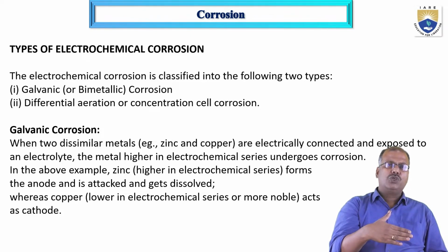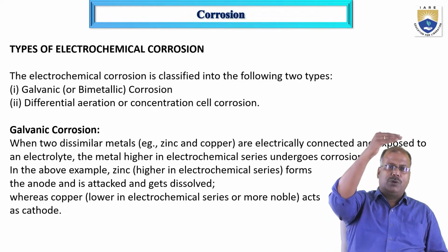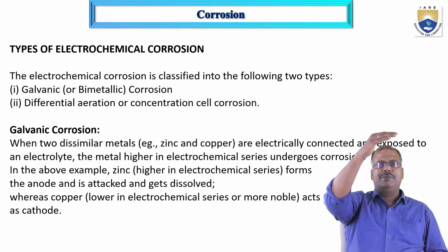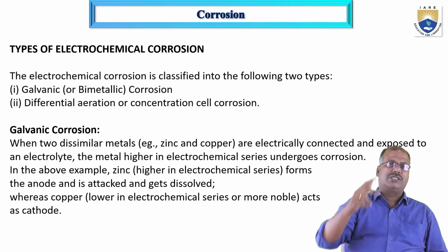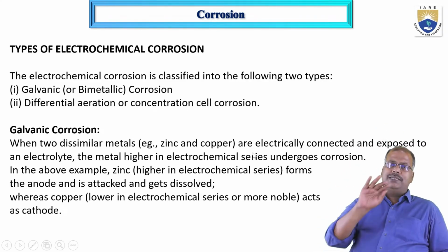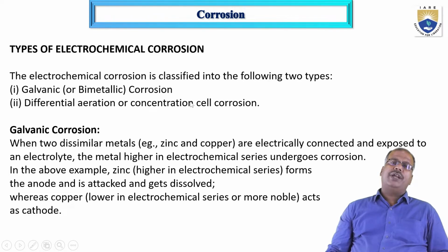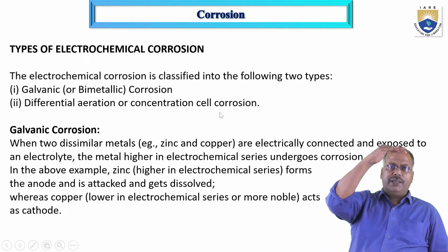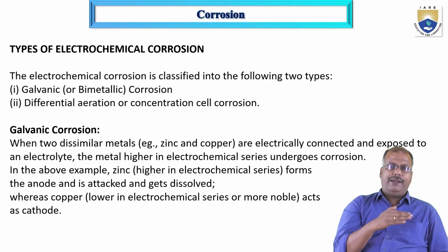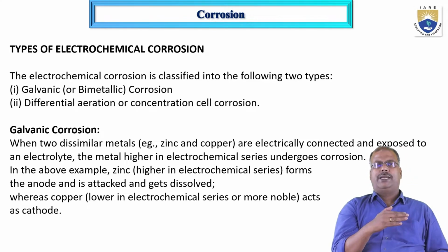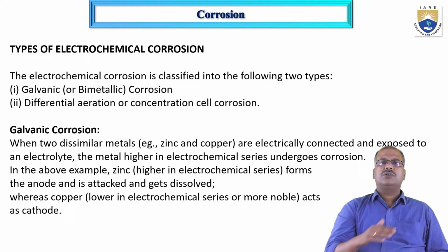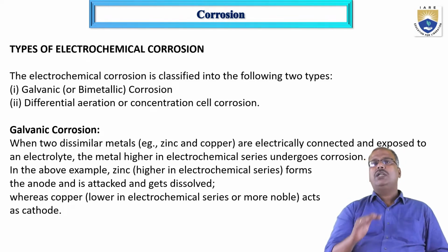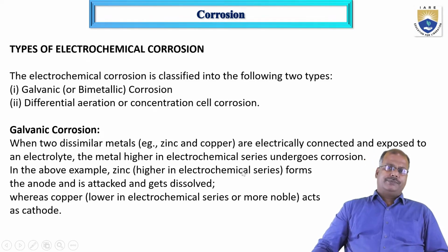One end contains noble metals like Au, Ag, platinum and their alloys, which don't undergo corrosion. The other end contains magnesium, aluminium, zinc and their alloys, having more negative potential. That series is called the galvanic series.